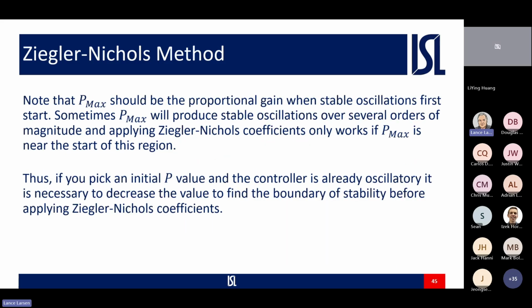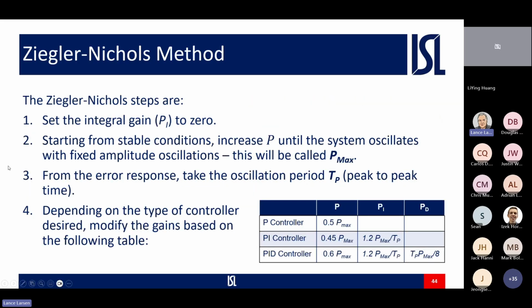One thing to note is that before, we've been doing the PI controller, which doesn't use an integral gain term, it uses a tau term. The equivalent of setting the integral gain to 0 is to put a very large value for tau, the time constant for the delta t. Just set that to a very large value, so this is about 0.